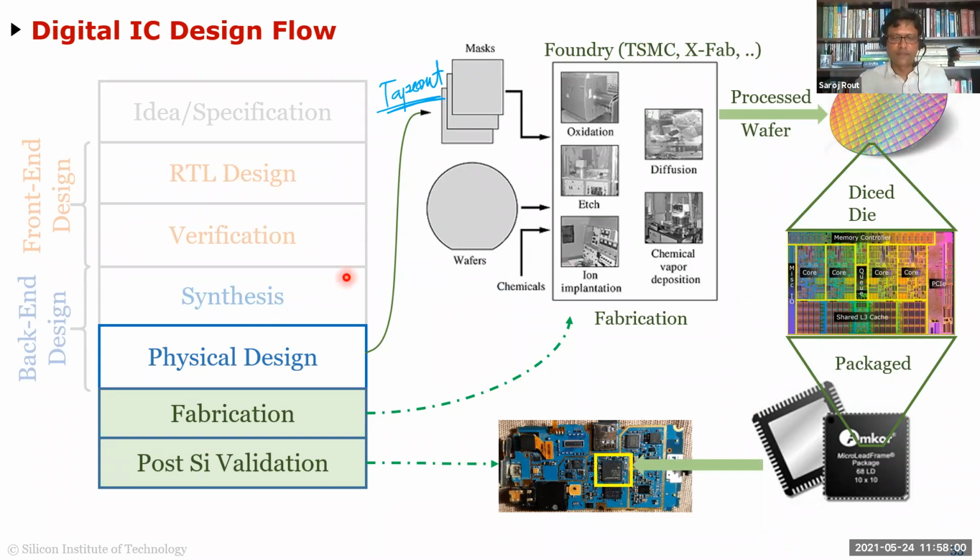Okay, so this is, as I said, a very simplified digital design process. I mean, this is both custom and semi-custom, just that in semi-custom, these steps here, the RTL design and verification and physical design process, have more sub-steps to them. Other than that, pretty much everything remains the same. But the whole idea of the flow, no matter whether you're doing full custom, semi-custom, digital or analog, the basic steps are obviously the same. You have to do a design, verify it, you have to have a layout.